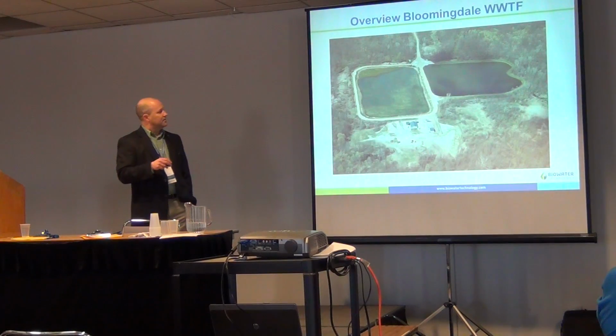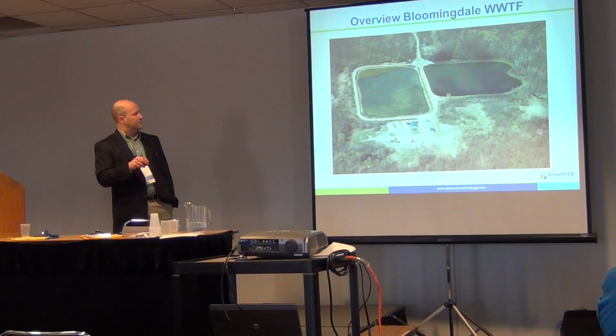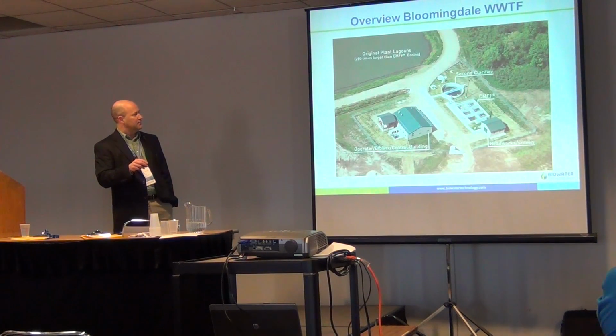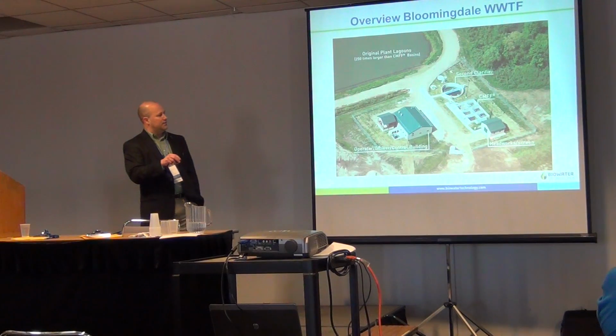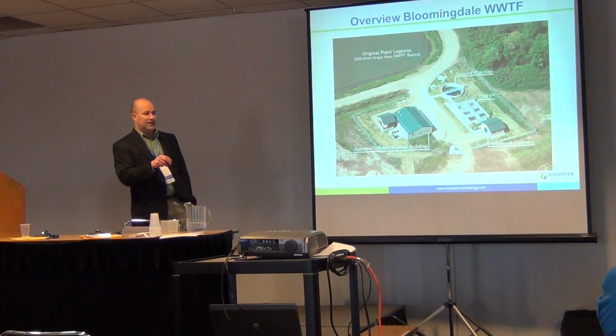So here are the two existing lagoons. This is an aerial view. You can see right on the outskirts of the lagoon is where we placed a whole new treatment system. If we zoom in a little bit, there's the headworks building. That contains the screen that gets it down to 6 millimeters, followed by 2 trains.